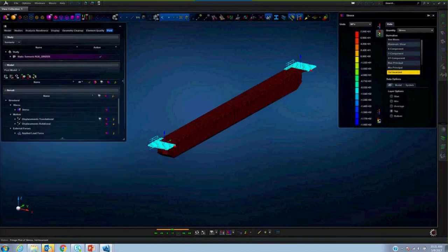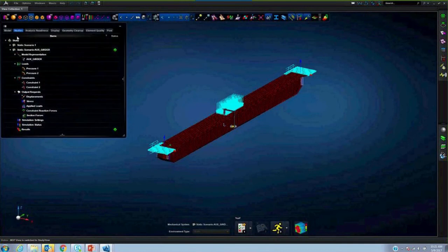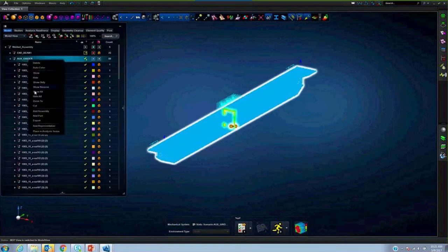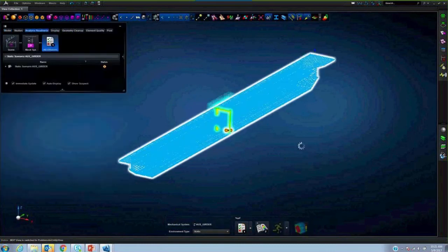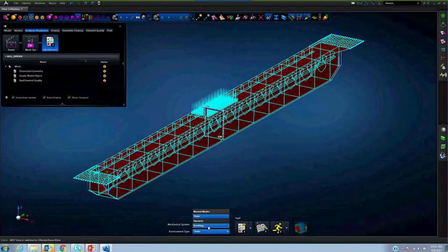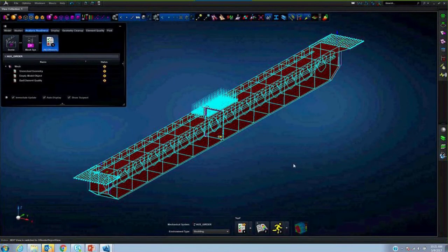So we have done the linear static analysis. If I would like to conduct a buckling simulation for the same subsystem, is that easy? I can simply go and set the context of the same subassembly. Now I can toggle, instead of static analysis, to buckling analysis. Now the model is ready to run the buckling simulation, and there are no other errors associated in the model when we change the context to buckling. Let us quickly run even the buckling simulation.